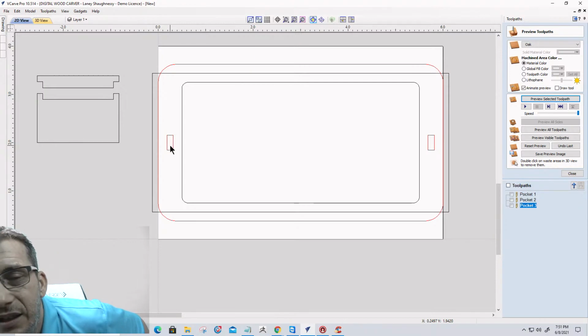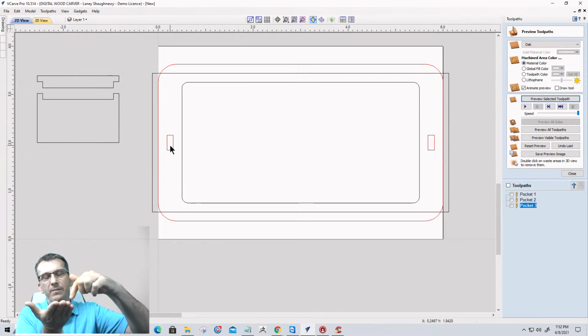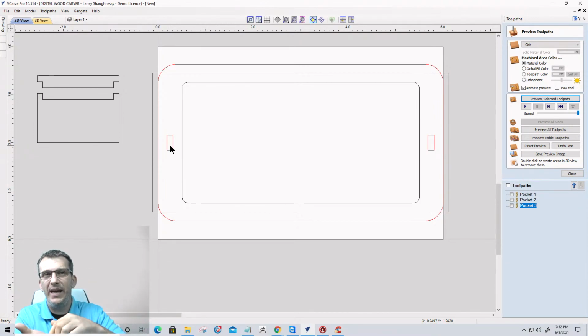Now the lid is going to get cut. Basically, when we do all the work, we're cutting from the bottom side. We're cutting the magnet slots in it because it gets magnets as well. We're cutting the magnet slots in there, and we're cutting the 2 channels on the 2 sides of it. So make sure when you are cutting the lid piece, the thinner piece, the 3/8 inch piece, that you choose the nicer side that's going to be the top, right? Because we're going to be carving on the bottom of the lid.